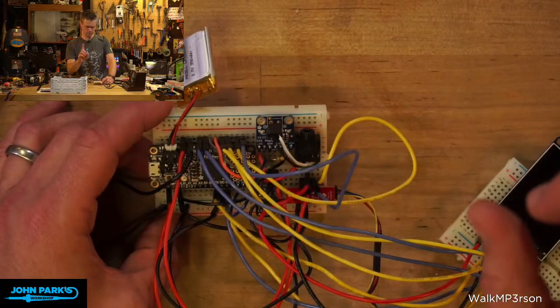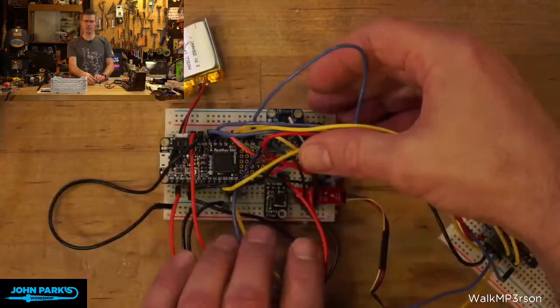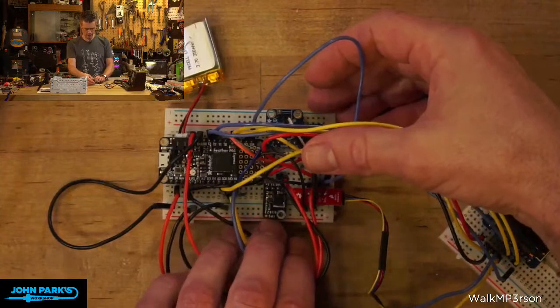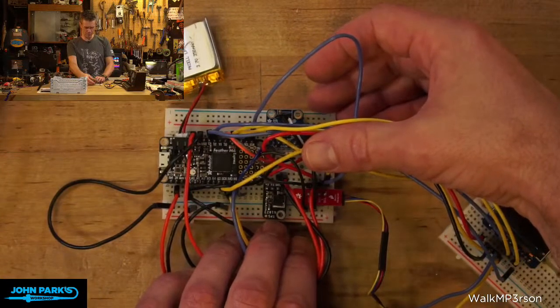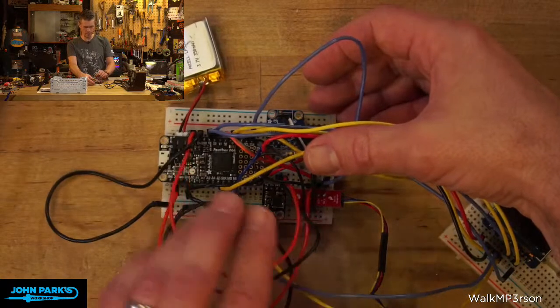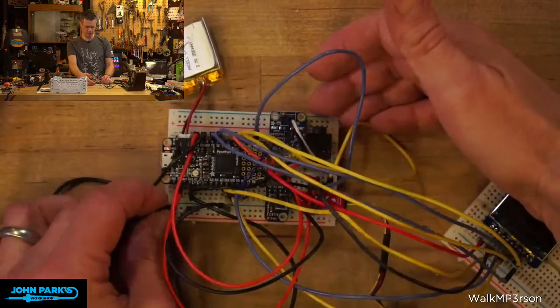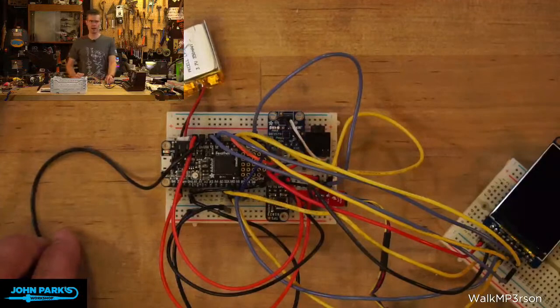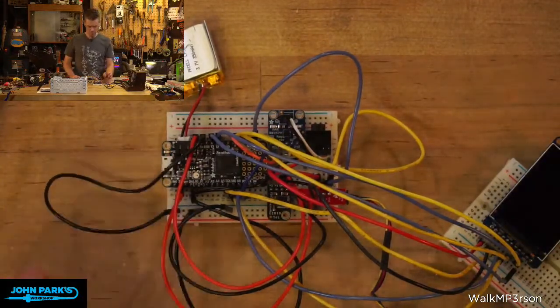And so to do that right now, I'm using this little, we call it the mini boost, and that boosts whatever you give it up to a nice clean 5 volts. So I'm giving it 3.3 off of the battery pin. So this will run off a battery. In fact, if I take off the jumper of the enable pin to ground, this is running now. I'm going to turn that off again for now.